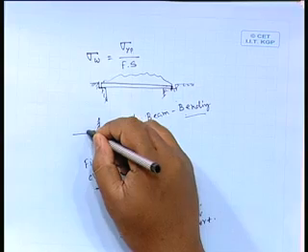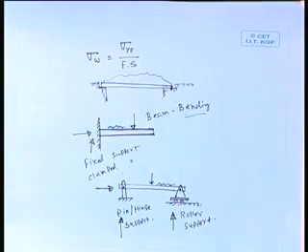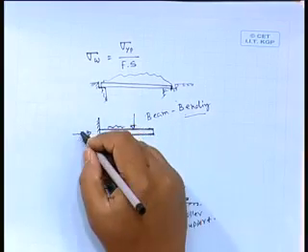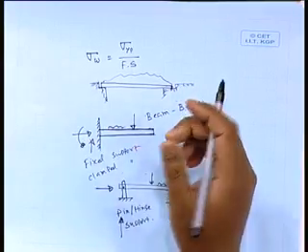Now, if you come to the fixed end, it is basically absolutely blocked, it will neither allow to move horizontally, nor vertically, nor allow to rotate, because it is absolutely fixed there through some strong welding or some arrangement. So, it has horizontal resistance, so a horizontal reaction it will get, vertical resistance is there, a vertical reaction it will get, plus some moment will be generated, because it will not allow to rotate.